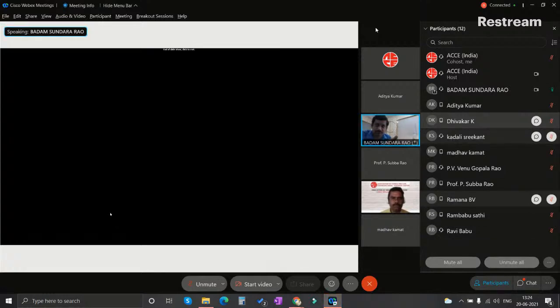And there are some research papers pertaining to this question also. You can obtain them from the net itself. I think one paper is there with the variation of 0.25B, 0.5B, 1B, 1.5B, and 2B. This variation is nothing but increasing the depth of the sand cushion or the sand zone, whereby you are transmitting your shear stresses to the maximum in a stronger soil compared to the weak soil, thereby your shear resistance and bearing capacities are much more refined. It comes under the two-layer soil system, and the settlements will also be much less, within the permissible limits.